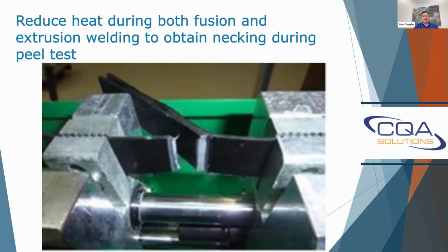And so I believe that's a great first step, and I think more people should be taking this approach and trying to be proactive, and be less worried about the peel and shear, but pay attention during trial seams. We don't want to have a high failure rate on the peel and shear, so there's got to be a balance. We don't want our destructs all failing again, but there has to be a balance.